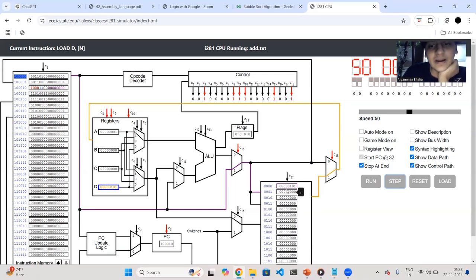Now that happens by, firstly, you have these lines here that denote the address that you want to access of the memory, and that's how this read enable fetches this value out, and that's the output that you get. And C18 is also configured in a way that this gets fed back to the register, and the selects are configured in a way that it loads into D. That's how our control logic is written.